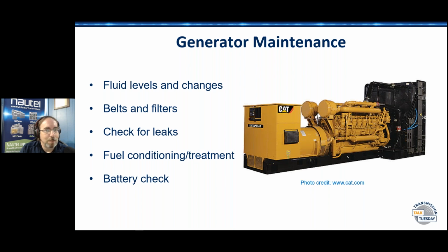And Mark Voris makes a note about putting hardware cloth over the radiator opening on the genset. Same deal, if you've got an indoor generator with a vent for the cooling air to the outside world, then that's absolutely something to do. Mark, if you've got a microphone, I'm going to unmute you, because you had thrown in a few other really good ideas specific to having water on the site and the hardware cloth to protect from hail. Tell me about it, you're out in the Midwest, so you see that stuff.